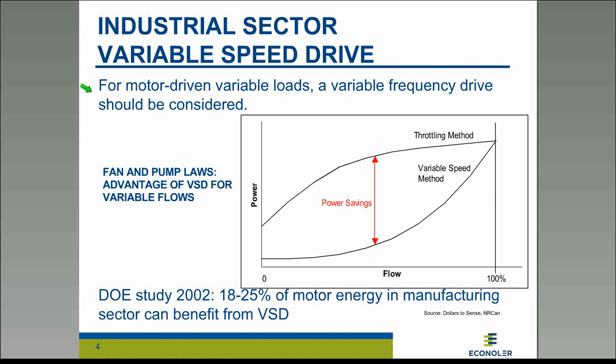One of the observations that several of you are probably aware of is that when we talk about motors, one of the biggest potentials lies in the installation of variable speed drives, especially if we are looking at centrifugal types of equipment, so fans, pumps, and some types of compressors also fall into this category.